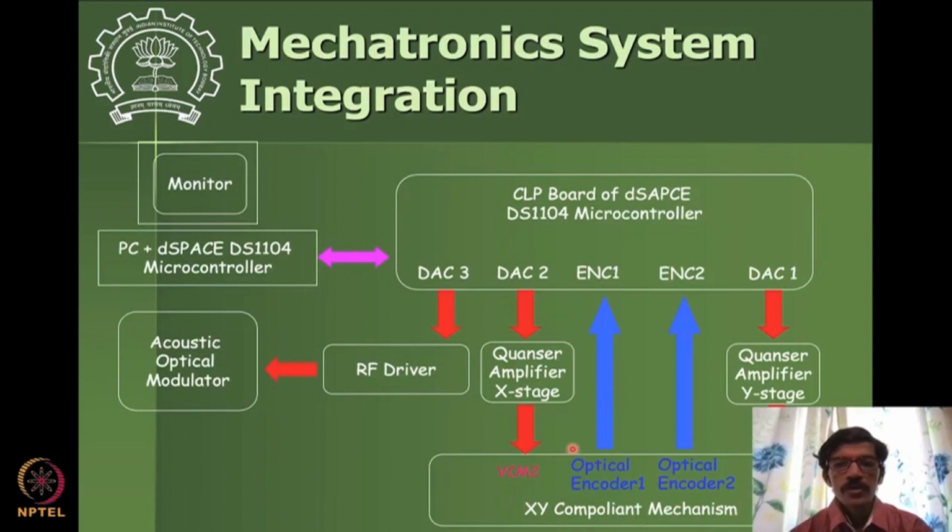Then you have these encoders, which are sensors in the system reading the data. We have seen a lot about encoders, how they work and how they can be programmed. These are optical encoders, but now they are linear encoders. Again, they are non-contact, so the entire system has no friction, and that's what gives us a way of positioning with very fine accuracies.